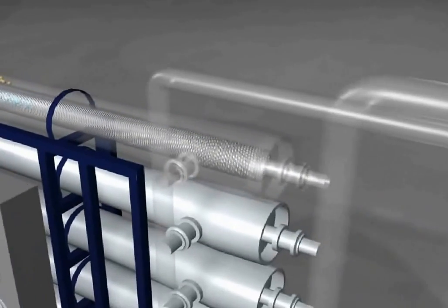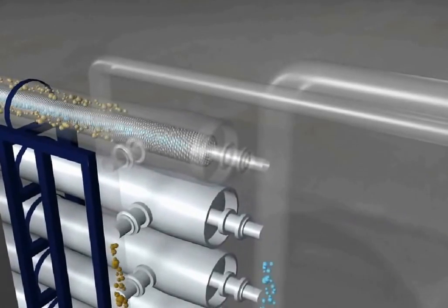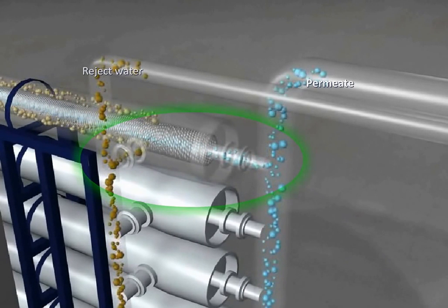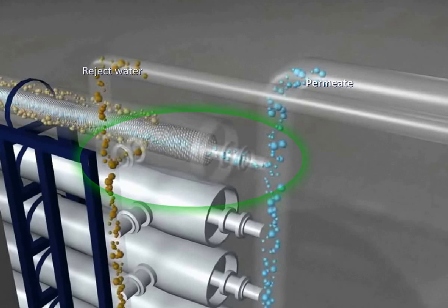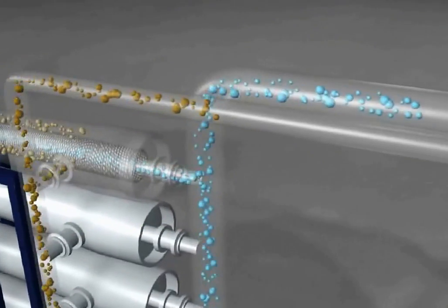Concentrate is the fluid containing the contaminants that are rejected by the filter. This concentrate is directed to the reject water tank, where it can then be transferred. The feed water continues to flow through the reverse osmosis membranes. The contaminants are trapped in the outer shell of each membrane. The concentrate reject water here is highlighted dark brown. After filtration, the water that has permeated through the membranes into the inner shell is called the permeate water, and here is highlighted blue.